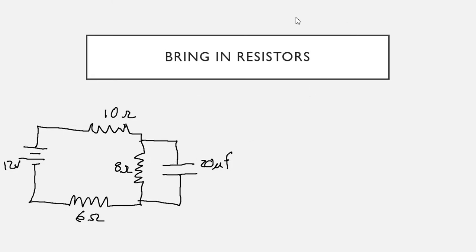And let's say, just for the sake of argument, there was a switch right here, right? And if initially this switch is open and it's in this position, there's no current flow, then if there's no current flow, there's no way charges get to this capacitor. This capacitor would be fully discharged. If I close this switch, so now this switch is closed, well, now there's a path for current flow, which means the capacitor is going to charge.